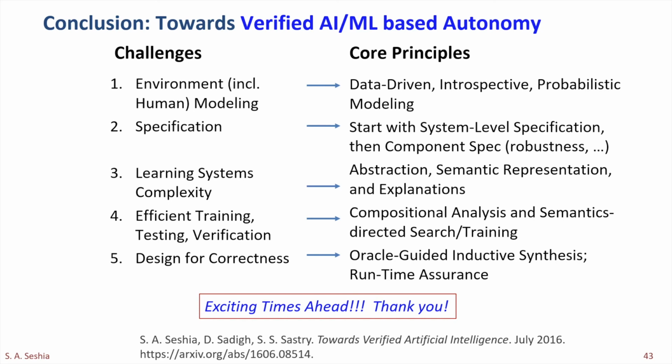But it would be very easy to add, for example, a new sampler to Verify, which computed that notion of coverage for all the runs you've done so far, and then use that to decide which test cases to try out next. And that is a direction, as I think Sanjit mentioned, that we're definitely interested in heading in, trying to do more white box analysis of the system. Whereas to start with, in order to be as scalable as possible, we treated the system as a complete black box. And I should add that the Halton sampling method, the low discrepancy sampling, was a technique that we borrowed from literature in the robotics community, where it's been found useful for things like sampling for randomized planning. So sampling in spatial environments.